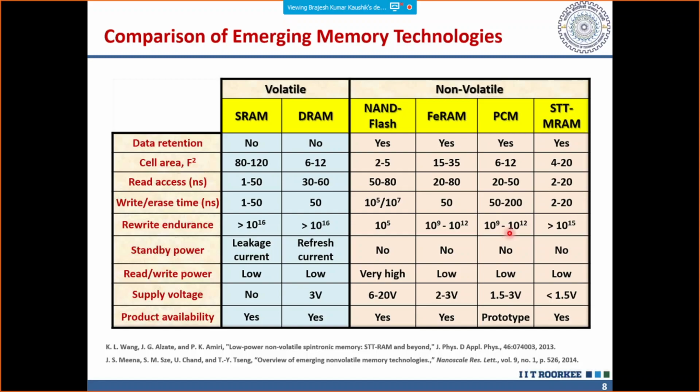As you move on with standby power, of course, your volatile ones are going to have some standby power consumption, whereas your non-volatile ones would perform well in that they do not require any standby power consumption. Inherently, they have that property. Other than that, your read and write power is quite low for STT, PCM, and ferroelectric RAM.